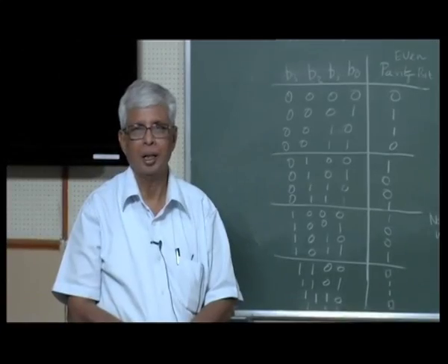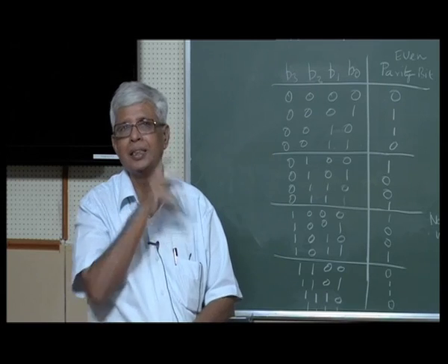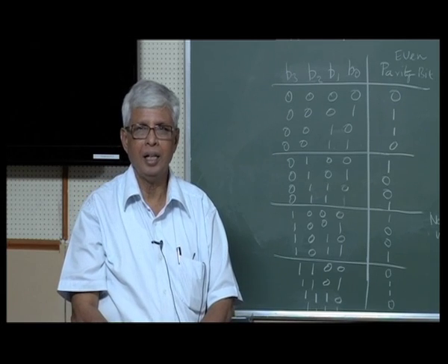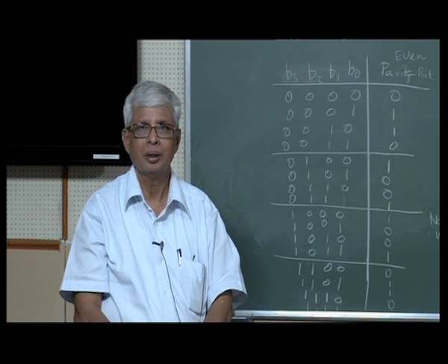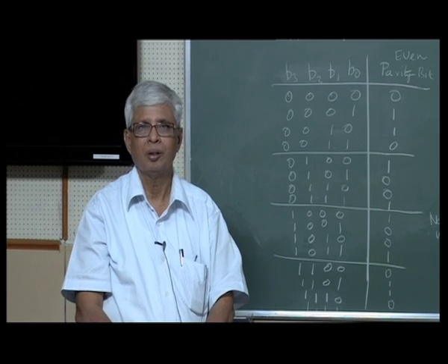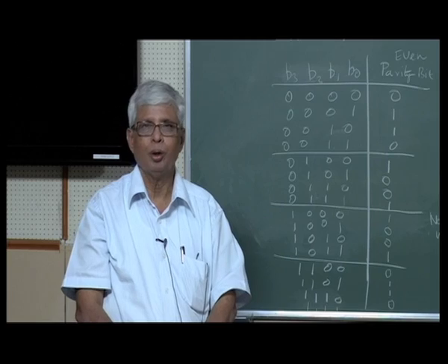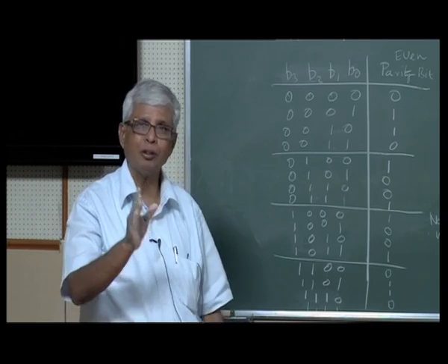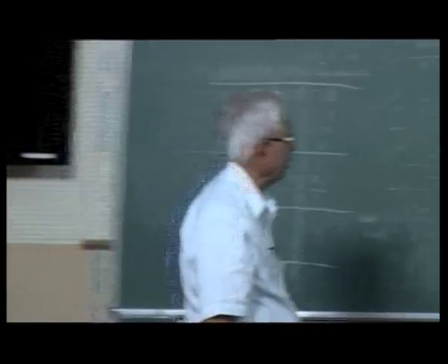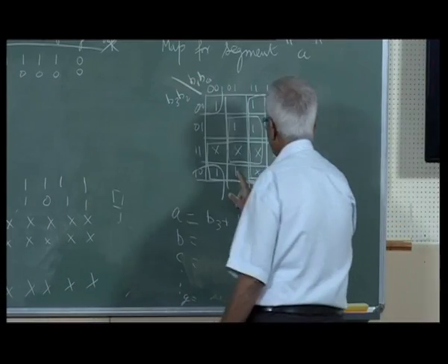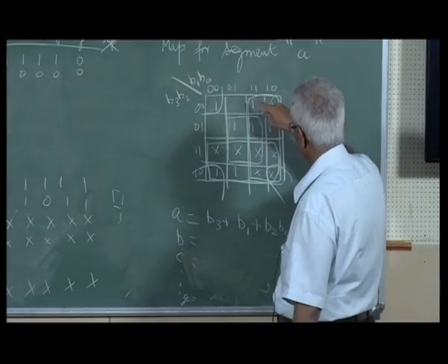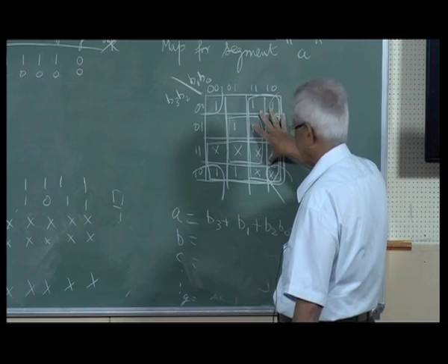Sir, in the K map of this 7-segment display, each segment separately, why have we used those don't care digits, that you cross one in that? You don't have to. If it's useful, use it. See, I am having these 8 ones.